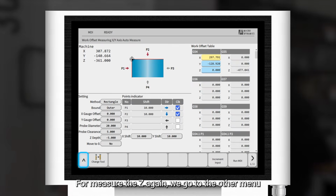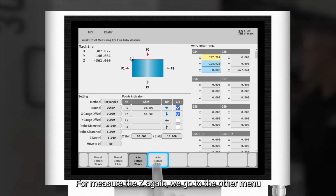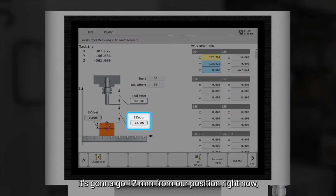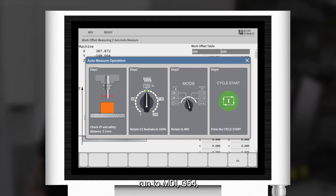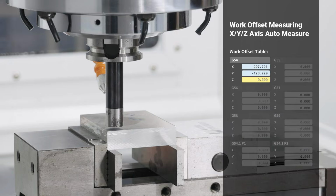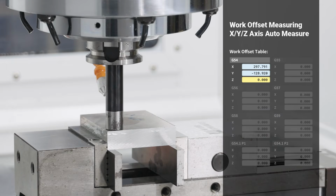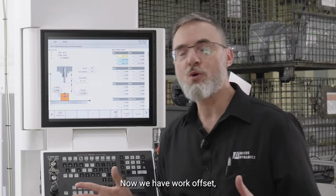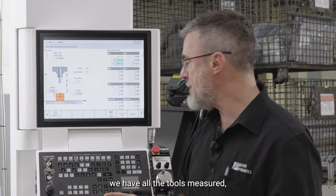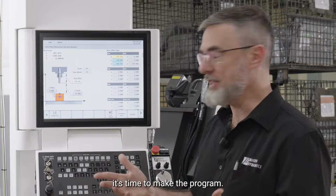Okay, to measure the Z, again, we go to the other menu. Automatic in Z axis. It's going to go 12 millimeters from our position right now. Run to MDI, 54, cycle start. It's already measured. Now we have our work offset. We have all the tools measured. It's time to make the program.